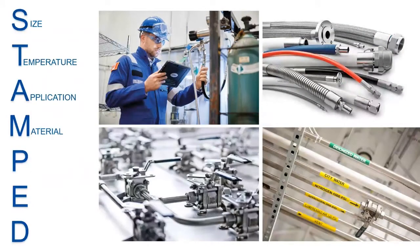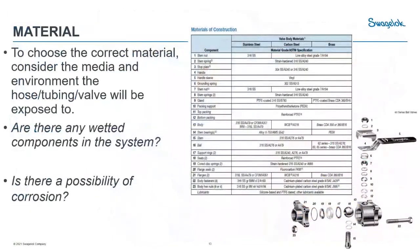Next, we'll go over material. So to choose the correct material, you want to consider the media and environment the product will be exposed to. Some questions you might want to ask yourself are, are there wetted components in the system? This is something you really want to focus on because you want to consider looking at your material, chemical, and temperature compatibility charts. Remember that a wetted component is anything your fluid touches.